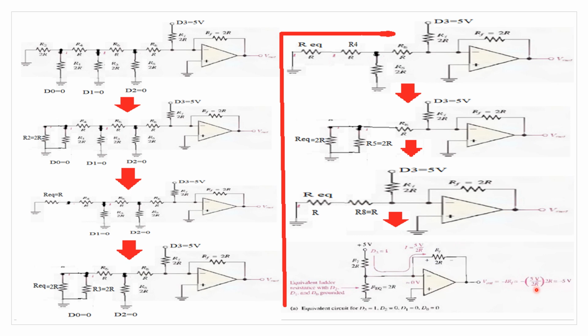So 5 by 2R into 2R. Here we have to put a negative symbol as we are giving input to the inverting terminal. So this negative sign shows that input is given to the inverting terminal. So the answer can be written as minus of 5 by 2R into 2R, that is equal to minus 5 volt.